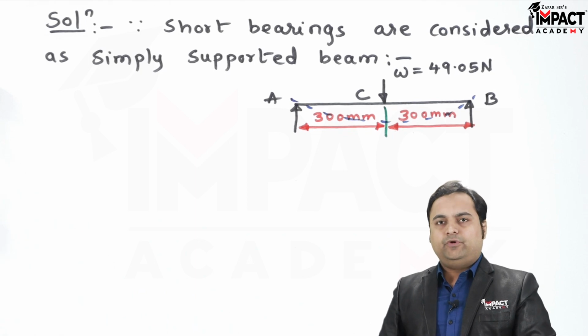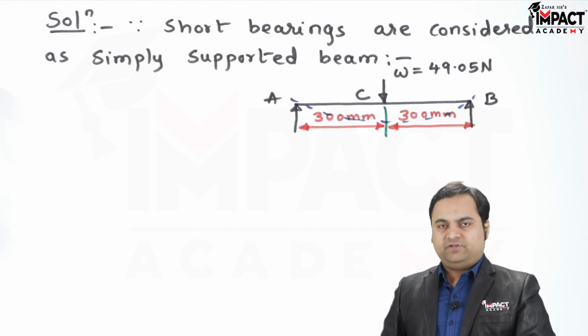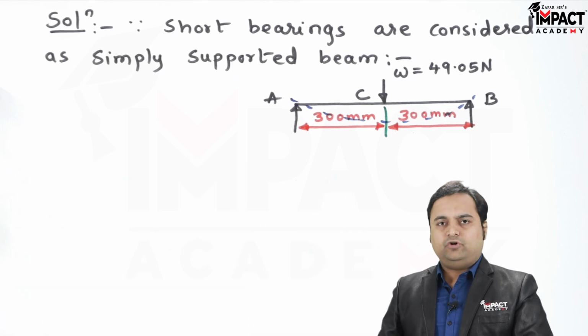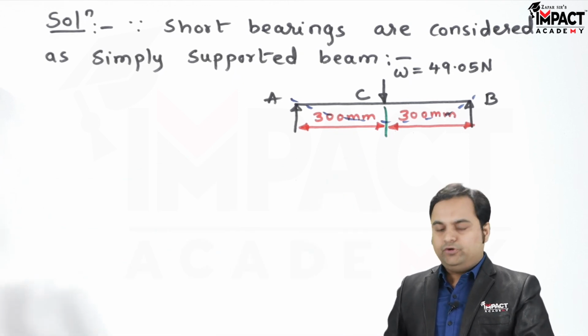So here what we are going to do, we are going to find the static deflection of the shaft first. Static deflection will be due to the weight which is kept on the shaft. Means right now the shaft is not started, just under the action of load it is going to deflect.